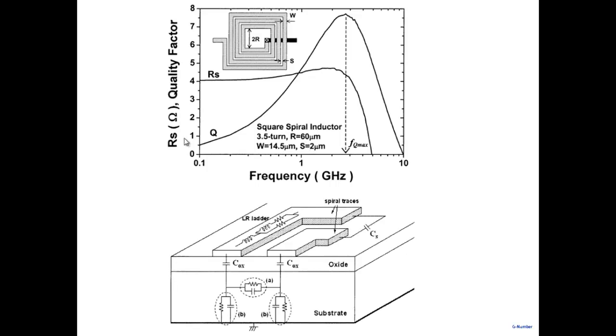So note what they're showing is, just look at the quality factor. This is 1 gigahertz. So if you are at 0.1 gigahertz, 100 megahertz, the quality factor is less than 1. Q is less than 1. Now, it's obvious that as I go to higher frequencies, the quality factor is improving, omega L. Omega times L, so as omega increases, the quality factor increases, but then there are capacitors also.